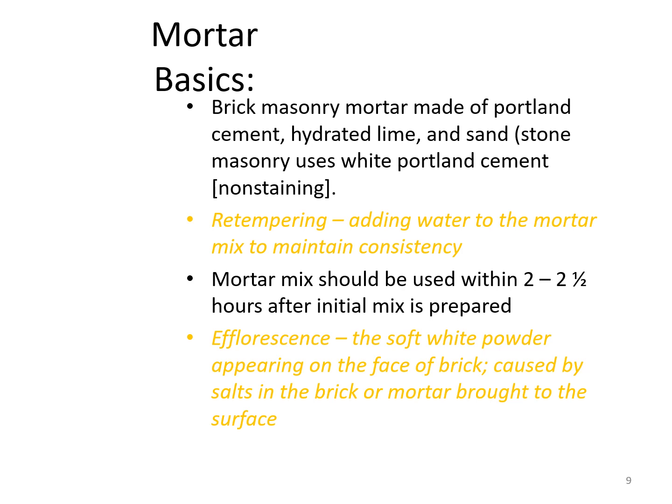Now, efflorescence. You've probably seen this. It looks almost like somebody put some powdery substance on the outside of the brick or the mortar. It's fuzzy. It almost looks like a growing mold, but it's efflorescence. It's caused by salts in the brick or mortar that are brought to the surface.